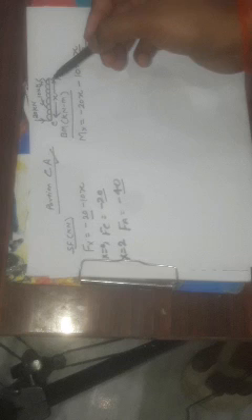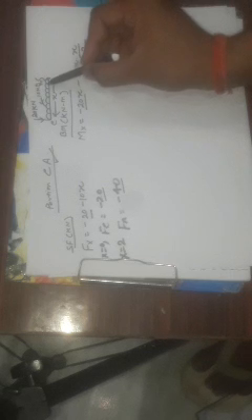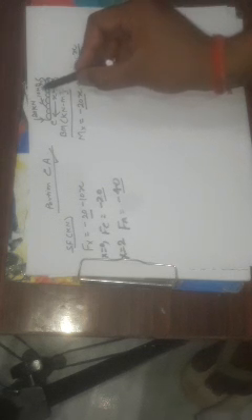Already we have studied from the sign convention that for all downward forces, the bending moment value is negative, right? Then minus 20x. The total weight of the UDL is 10x. It acts at half of x, so this 10x is at x by 2 from the section. So the moment of this 10x is 10x into x by 2, right?